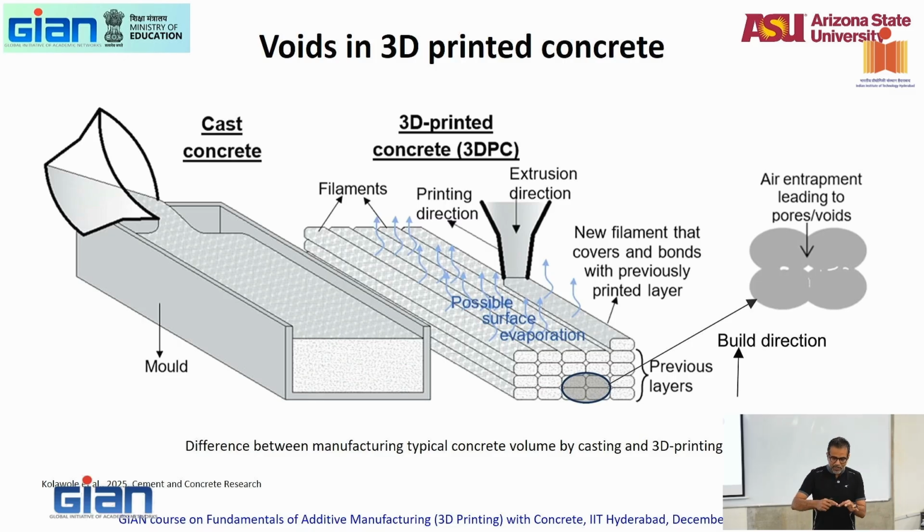Even when you extrude a layer that is rectangular, when it gets extruded, the material will settle down, the material will slump, and naturally you will start to get beveled edges, unless you have a brick type extrusion, which I showed you yesterday, for which you need an extremely stiff mix, right? And that also has its problems.